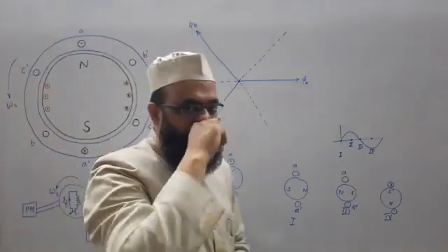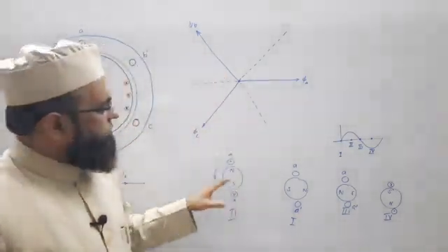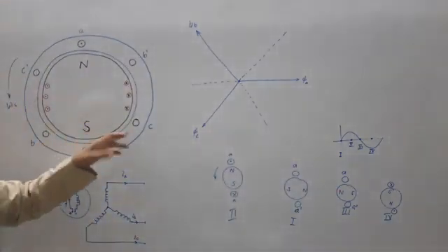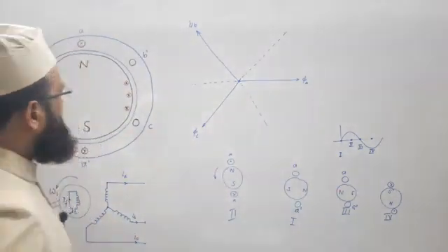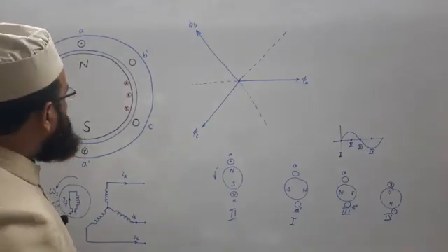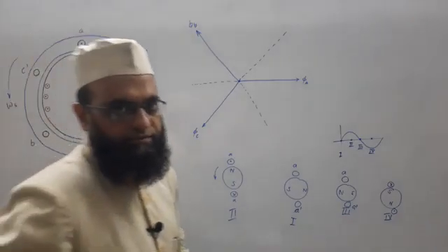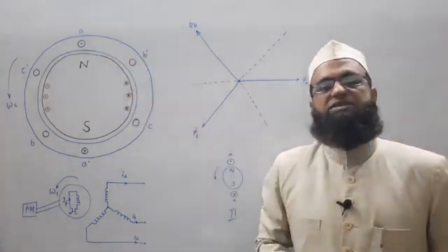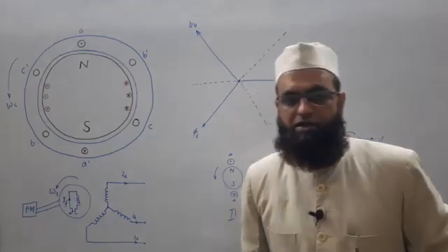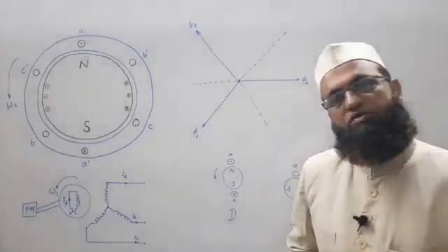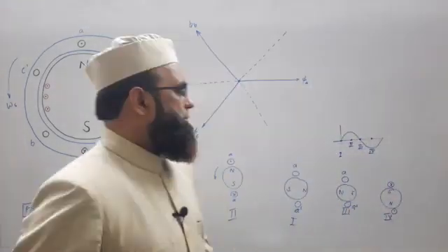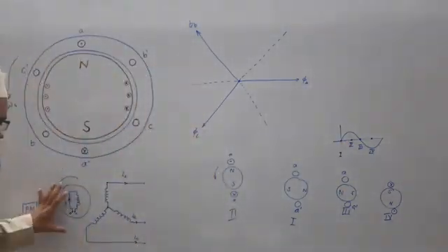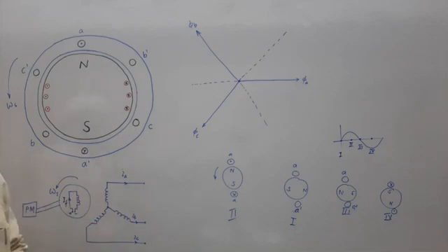So similar rotation will create similar cycles in, suppose phase A, we have discussed phase A. The same can be understood for phase B and phase C, and 3-phase EMFs are balanced in nature, as we can see that the alignment of the slots is in such a way that this is forming balanced winding and the rotor is being rotated at constant speed. So we have 3-phase such balanced EMFs in the 3 phases of the stator winding.